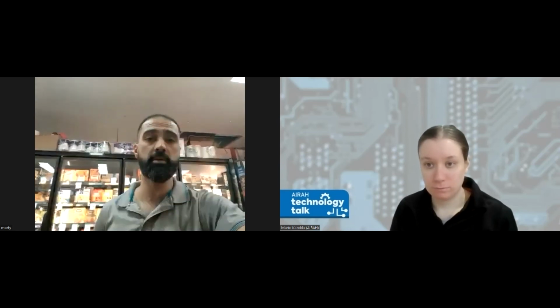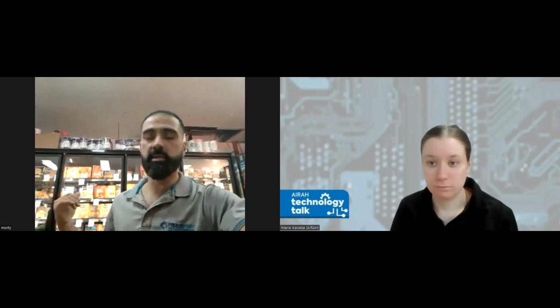I would have connected it if I had seen a port, but the liquid side is always going to remain the same, whether outside the evaporator, inside the evaporator, or at the system. It'll all equal 1. Unless you've got bad pipework design, you will have a pressure drop. But in this system we don't have any pressure drop because of the design conditions that we've applied.